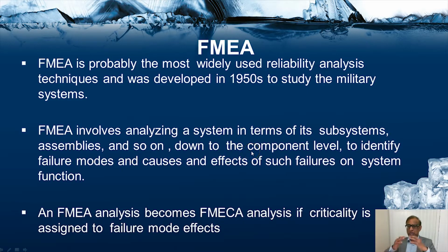So you start analyzing the system as a whole, and you try to partition the system into different parts and come down to the component level to identify individual failure modes, causes, and their effect on the system performance. And failure mode effect analysis becomes failure mode effect and criticality analysis if criticality is assigned